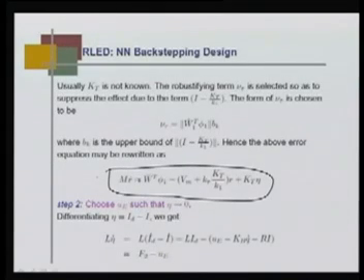Okay. So, you say that this I am representing by a neural network. This is actually, if m r dot is this, if the neural network exactly approximates the function, this is 0. So, then m r dot is this quantity, this is stable, then I have an extra term k T eta, and if eta is bounded, then the system is stable. So, now I select u e in such a way that eta will be bounded.